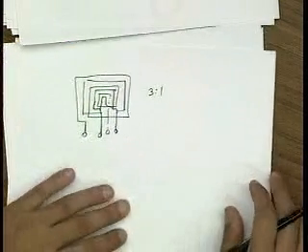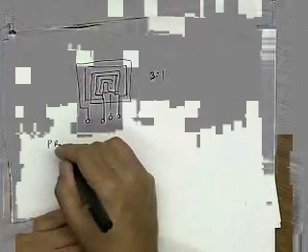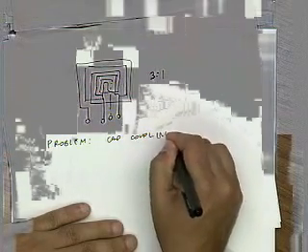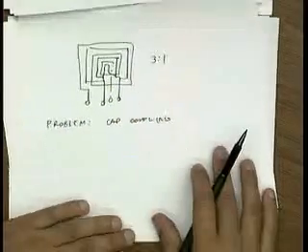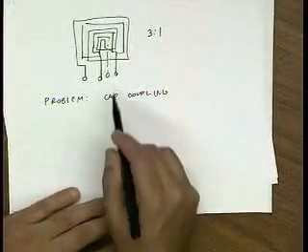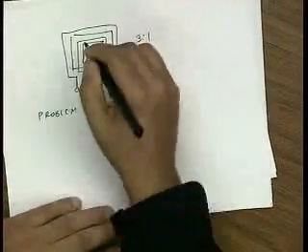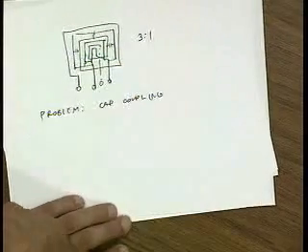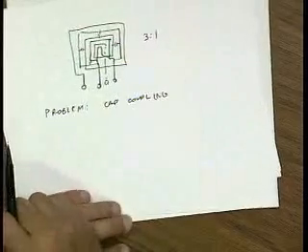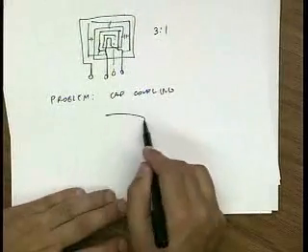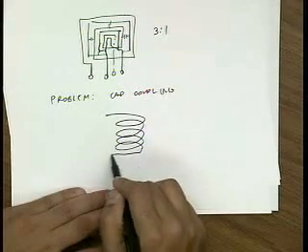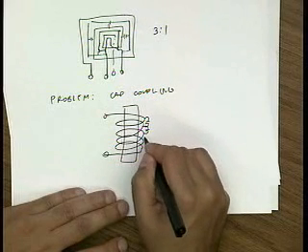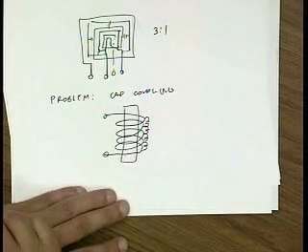Okay. Well, one of the problems with these transformers is capacitive coupling. Because I had to move these wires so close together to get good magnetic coupling, I'm going to get good capacitive coupling now, right? And capacitive coupling has the wrong phase. It actually cancels out the magnetic coupling, and it basically destroys the structure. Even for an off-chip structure like a coil, ultimately the self-resonance frequency is limited by turn-to-turn capacitance like this.